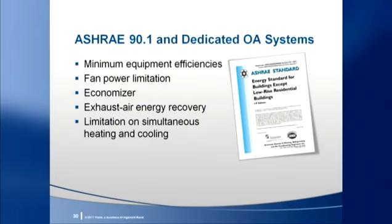There are 5 key requirements of ASHRAE 90.1 that affect the design of dedicated outdoor air systems. They are minimum equipment efficiencies, fan power limitation, economizer requirements, exhaust air energy recovery, and limitations on simultaneous heating and cooling. Let's investigate each of these.